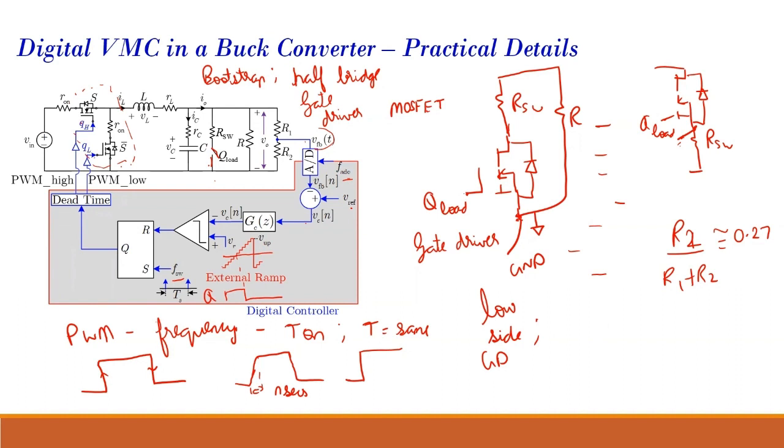Even if it was very smooth and you do it quite fast, it may be in the range of milliseconds. It will be changing like this. There will be some time. This is known as your slew time, that is in the range of milliseconds. But in the case of a MOSFET, it is in the range of nanoseconds.